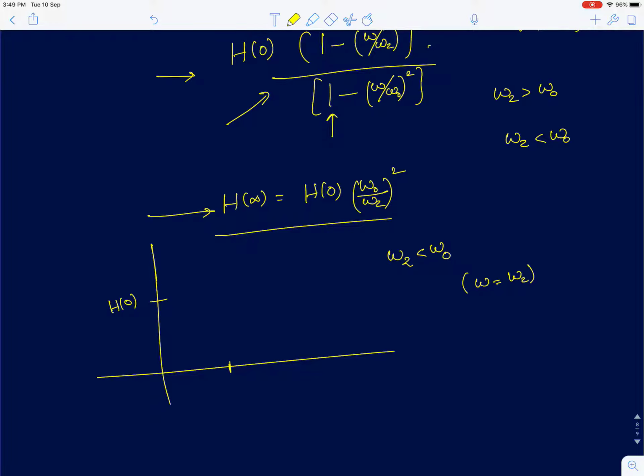It actually becomes 0. So for a first order system, when we discussed first order poles and first order zeros, the transfer function really doesn't become 0 at those frequencies. Because when you substitute s equal to j omega, you would get a complex number. But here, for a real frequency, you are going to get a 0. So which means if I feed a sinusoid of that frequency omega z to this system, you will get 0 output of the system. And similarly, if I feed a sinusoid of input omega naught, you are going to get an infinite gain. The sinusoid is going to be amplified, which we already discussed in the last lecture. And how does it come about?